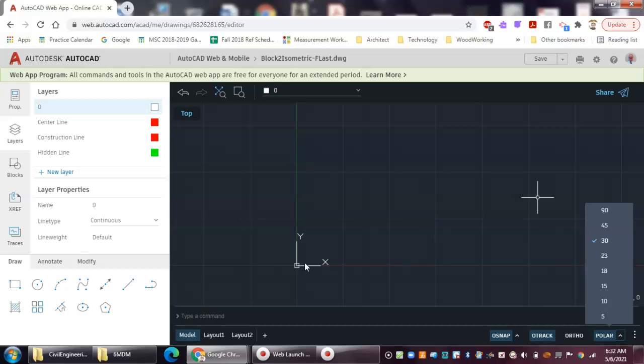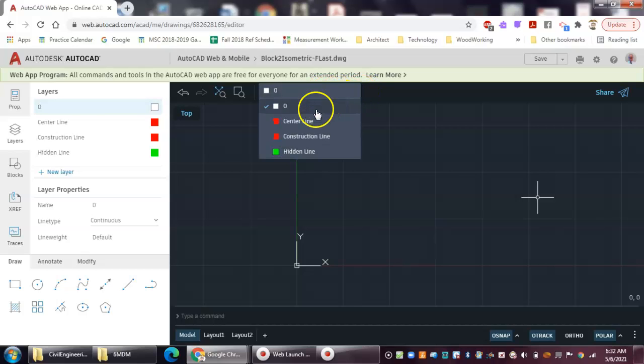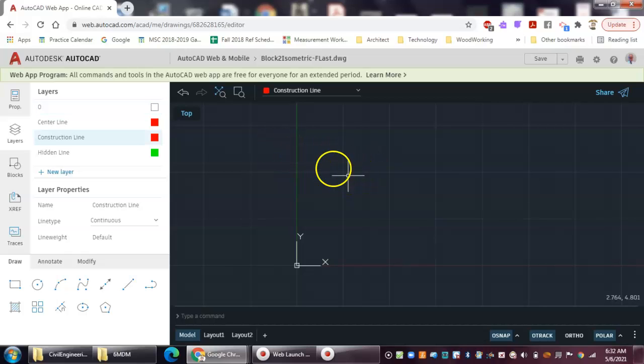And in the isometric drawing, even though we're tilting those edges of the block back at 30 degrees, the length of the lines stay the same. So we're going to first start to draw, and I'm just going to go back in. I want to draw my construction line layer first, and I want you to see how I kind of block things in and then use clues to know where lines should fall in these particular drawings.